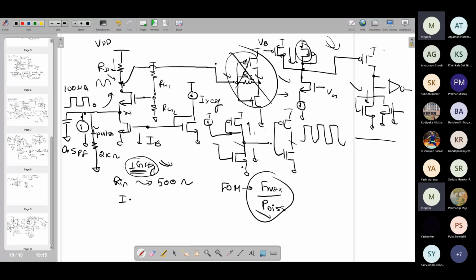So in many cases we have looked at the DC consideration assuming ideal current source behavior. Like in even this kind of load, we have said that the moment you connect this particular load, it is a current source in parallel with that connected load. So here we have assumed that this is acting like an ideal current source. So if you bias it with some IB, it will exactly take that IB, and the rest of the I tail current minus IB will go into that. That may not happen exactly. It will have some difference because of channel length modulation.